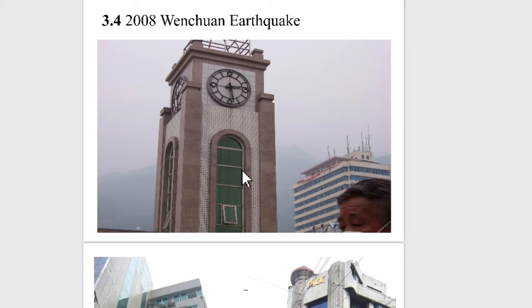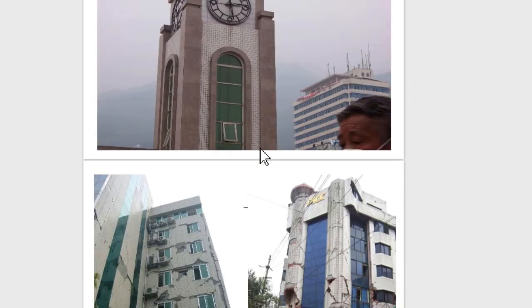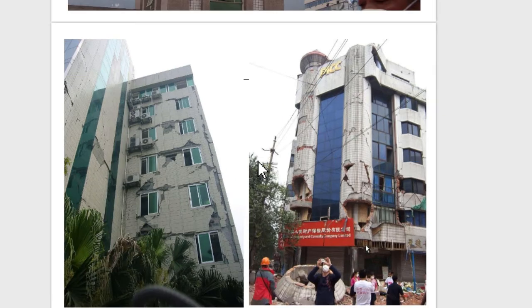So, firstly, when the earthquake happened at this time, as this picture shows, a lot of buildings collapsed and some walls are destroyed, especially the corner wall. Because a structure has some rotation response, the corner wall and corner columns will experience large displacement and large damage.